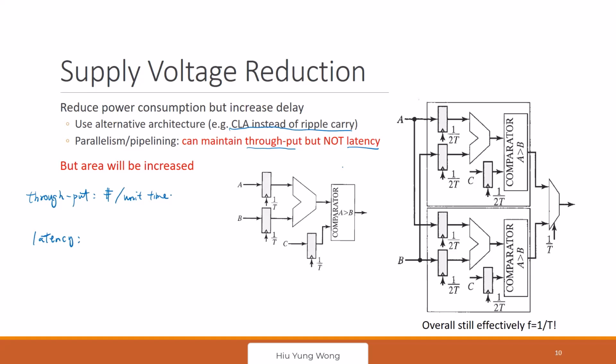That is the throughput. So for example, my DRAM is slow, the connection, one bus, maybe it's 100 megahertz. But if I can design my DRAM so that it has 10 buses, then what is the throughput? It becomes 1 gigahertz. Okay, so yes, it is slow, but the throughput is high.